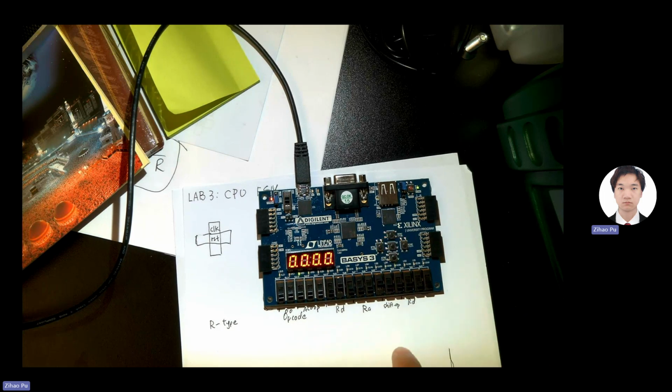So on the first push, it goes to a decode state. But as we mentioned earlier, the decode state is not the finish of the arithmetic instructions. So I give it another push. Now we have the data on the data bus, and you can see the result is here. Is this finished? No, because this is the state of writing back, which is the WB state. So you need another push to finish this instruction.